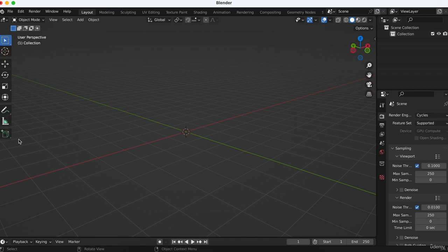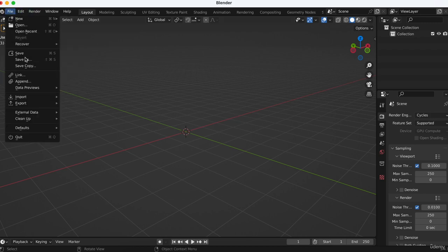When you press T, you have this, and also if you want the timeline, and also if you change, at first it is EEVEE, and I change it to Cycles because I want all my renders to be rendered by Cycles. So I put this, and now to save, you go on File, Defaults. We want this by default, and you do Save Startup File.